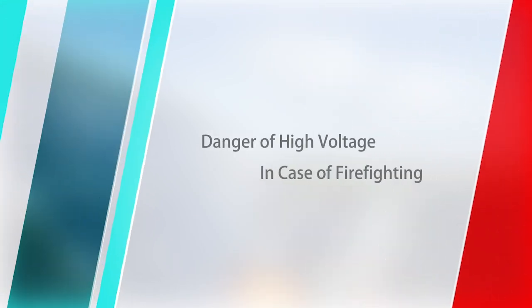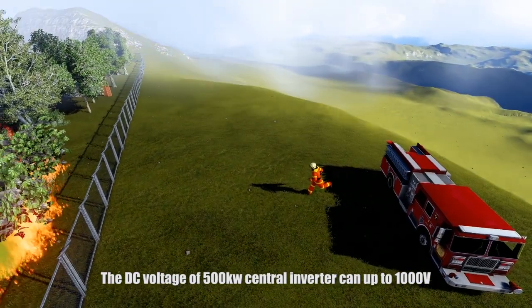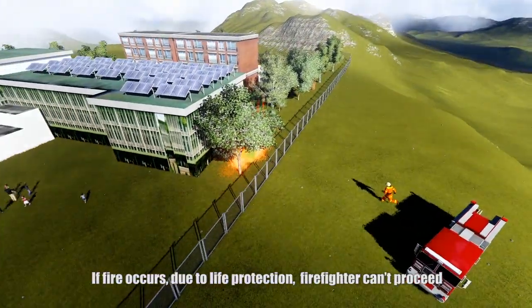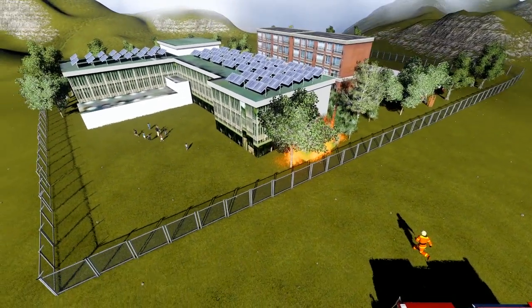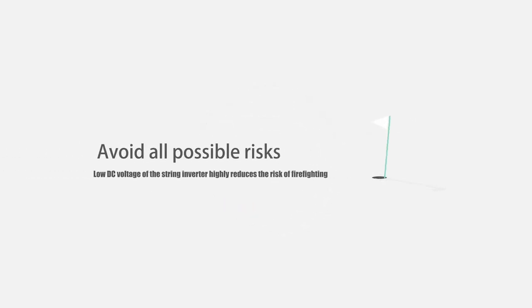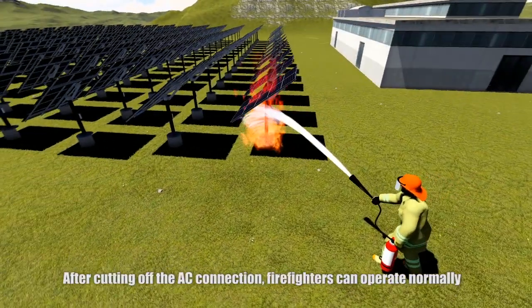Danger of high voltage in case of firefighting. The DC voltage of a 500 kilowatt central inverter can be up to 1,000 volts. If fire occurs, due to light exposure, firefighters can't proceed with the standard firefighting protocol, which might cause severe property damage. But with a string inverter, the DC voltage is much lower, mostly under 40 volts. After cutting off the AC connection, firefighters can operate normally.